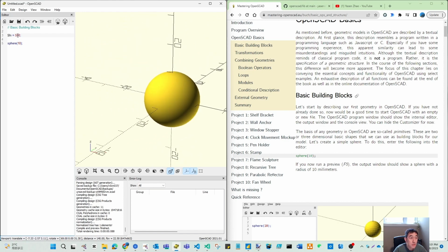If you have a bigger number, then you can see it's a very nice smooth ball. But keep in mind that if you have a larger number of faces, when you do this render, it will get slower. So by default, when you do the modeling, make this a comment, and in your last step, when you want to export or render your model, you can set the number of faces. Then that will give you the nice finished model, but don't sacrifice performance during your modeling work.